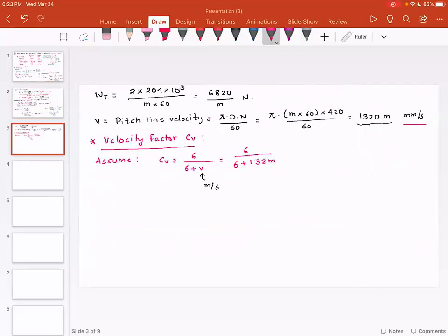So let's calculate that. L is equal to dg, which is the diameter of the gear, divided by 2, that gives me the radius, divided by sine of theta gear.